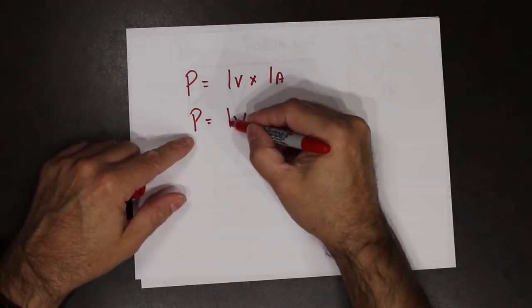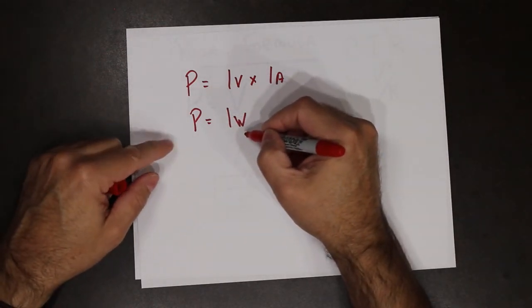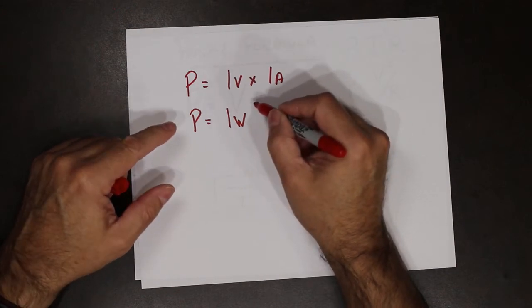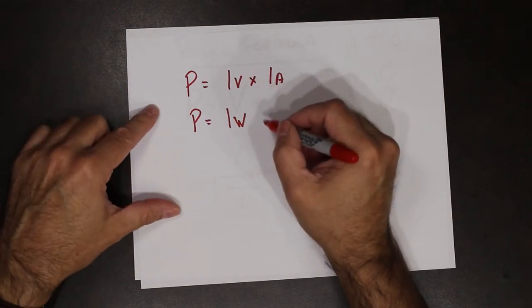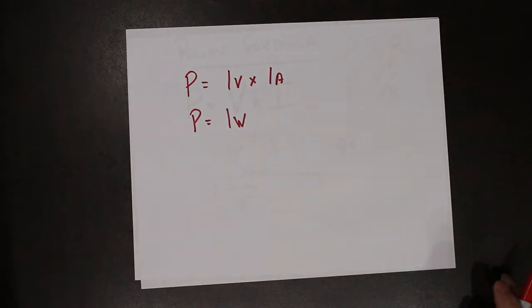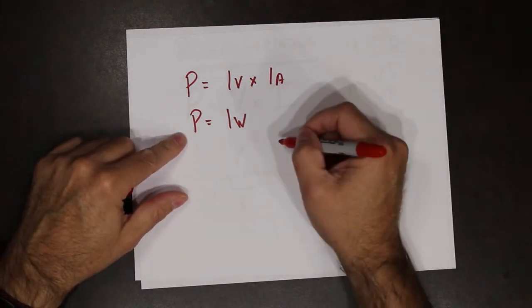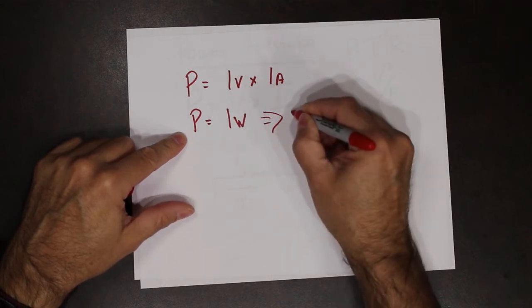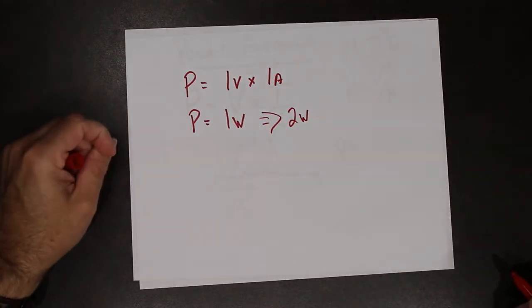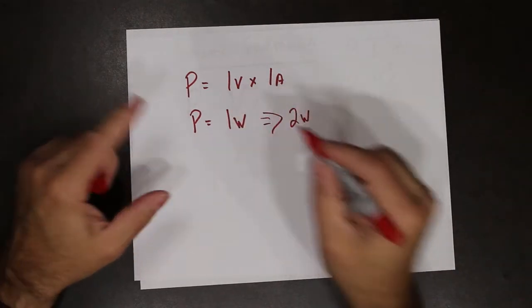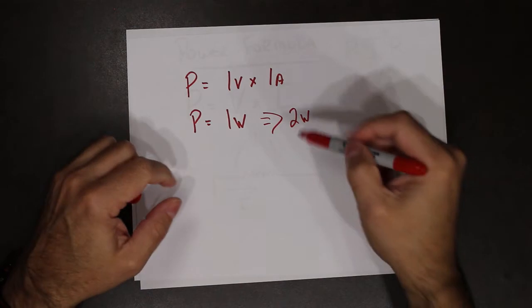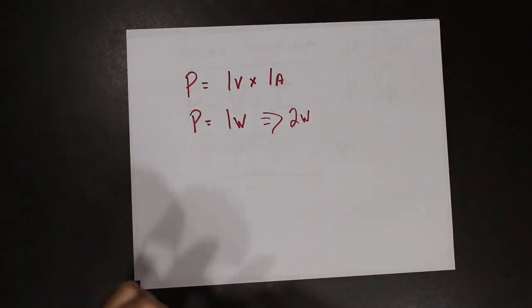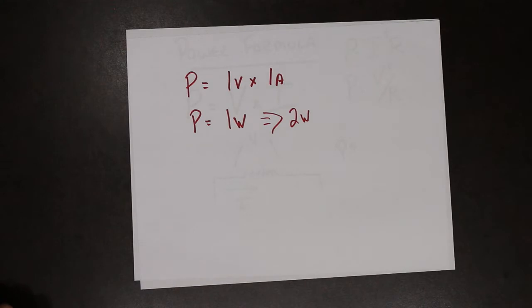So we won't put a 1 watt resistor there because we know that it will dissipate 1 watt under normal circumstances. So when picking the physical size of the resistor, we would actually go up one. So instead of a 1 watt resistor, we might put a 2 watt resistor there. So we know that it's going to get rid of 1 watt of heat, plus we have put in a little bit of a safety. So we've actually oversized it a little bit just in case something was to happen.